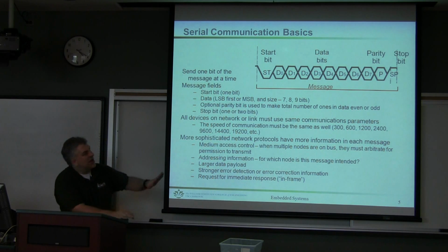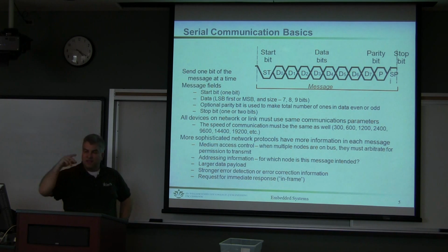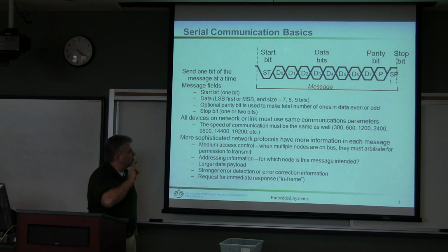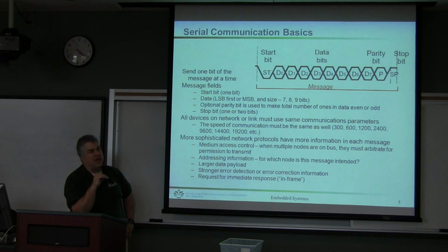So what communications designers do is send a start bit that says, now start your timing. We agreed on a certain speed, and I'm going to be sending a certain number of bits. By the way, it also pads it at the end with a parity bit, which allows you to check things. And then at the end is a stop bit.